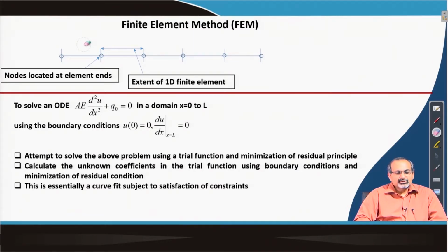Now, we will look at the solution of an ordinary differential equation here in order to understand some of the basic concepts of the finite element method. So, we have an ODE given by A E d2u/dx square plus q naught equal to 0, which needs to be solved in a domain x equal to 0 to L, using the boundary conditions that u at x equal to 0 is equal to 0 and du/dx is equal to 0 at x equal to L.